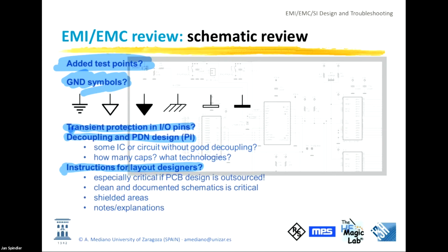And finally, and not less important, do you have instructions for the layout designers? Many companies are sending the design to external companies doing the PCB layout. So you need very, very good communication. If not, the design in the PCB will not be what you want in the schematic. You need to introduce comments. And of course, you need to specify things like, for example, shielded areas or isolated areas. This is part of the review from the EMC point of view, not from the functional point of view.